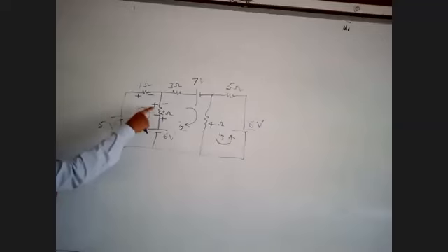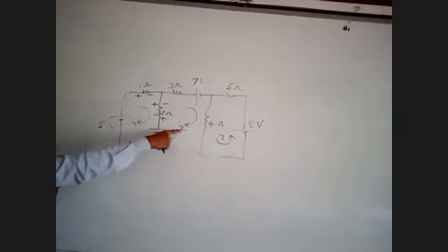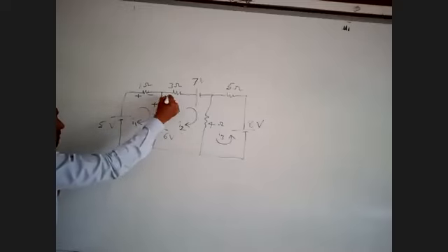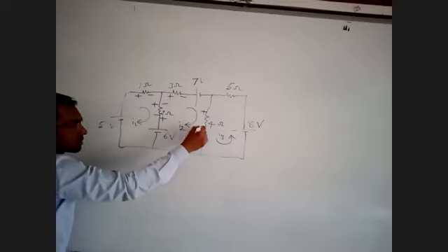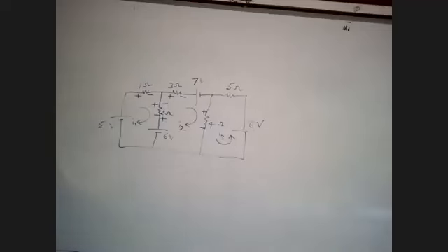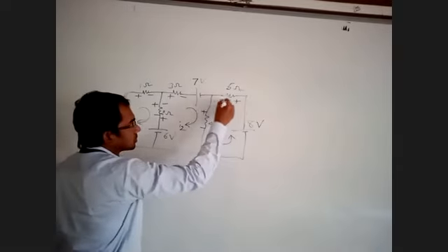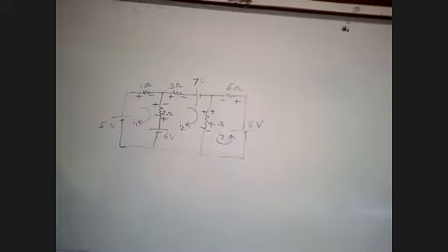This polarity itself indicates the direction. If both here are plus, minus, it indicates both are the same direction. Now these are opposite directions. I2 is flowing from plus to minus, in this direction. In the second loop, we have to see only the I2 direction. Now come to the third loop. Mark those plus and minus in the direction of currents I1, I2, and I3. That is your first step.